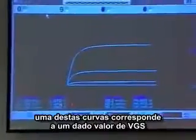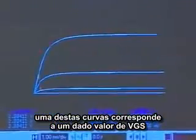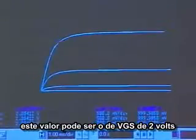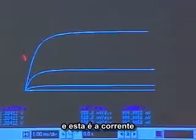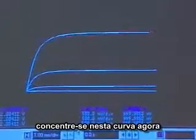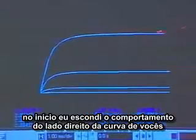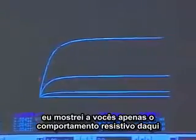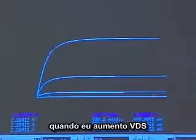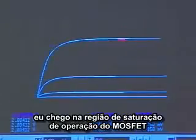So what do I have here? One of these curves corresponds to a given value of VGS. Okay, this may be VGS equals 2 volts. This is VDS, the drain to source voltage, and this is the current. So focus on this curve for now. In the beginning, I hid the right-hand side behavior from you and showed you just the resistive behavior out here. When I increase VDS to be much larger, the curve saturated and I got the saturation region operation of the MOSFET.